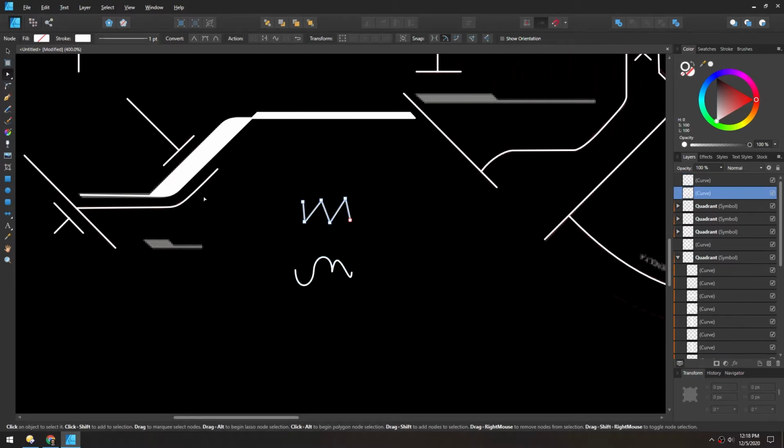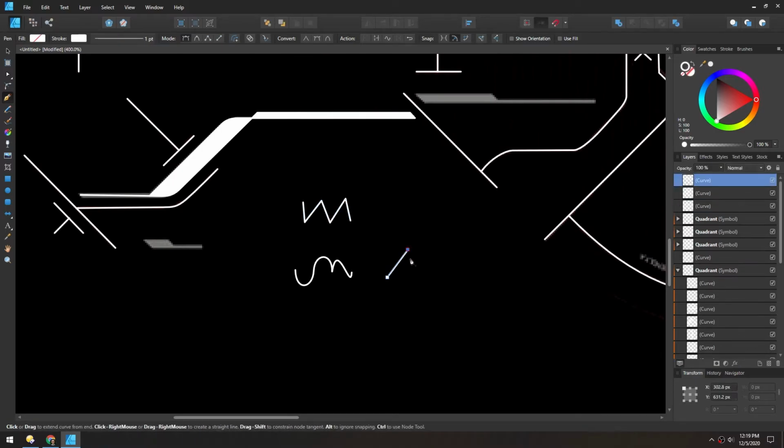And you can also do that while drawing. So with the pen tool, you can make a few hard edges, click and drag to make a smooth edge. And then if you hold Alt or Option, you can spin this around and then make all sorts of complex shapes. So between the Alt or Option key and just clicking or drag clicking, you can make really complex curves.